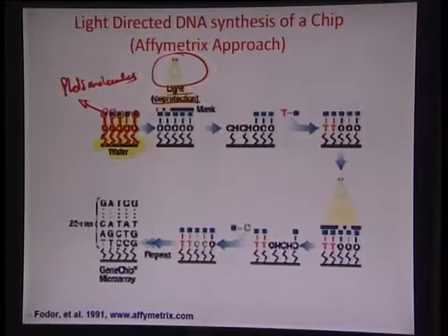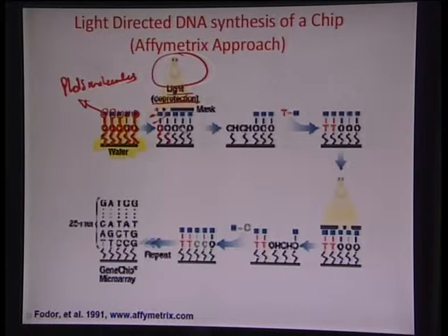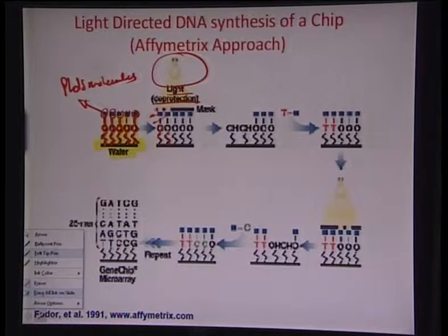Wherever there is a transparent via or structure, light goes in and decaps or uncaps these photomolecule layers. So you have deprotected this linker layer by using a light signal. You are deprotecting the linker layer in this particular illustration.